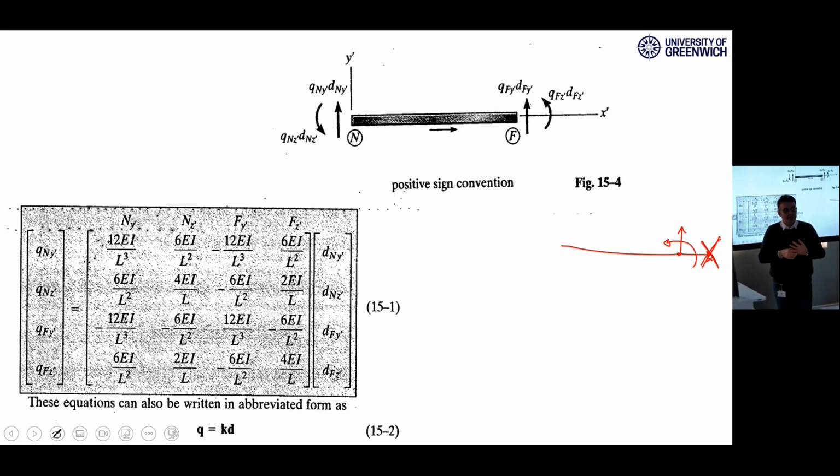If you remember energy methods, it had 4 different integrations: one for axial force, one for bending moment, torsion, and shear forces. Once we tried to solve some examples to calculate the integration of axial forces, the value was somehow negligible in comparison with the integration corresponding to the bending moment.